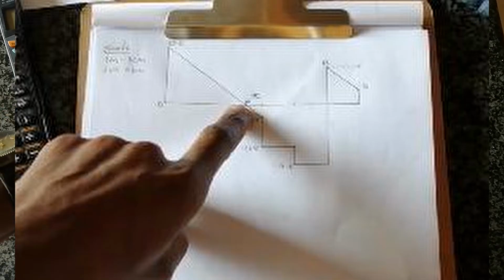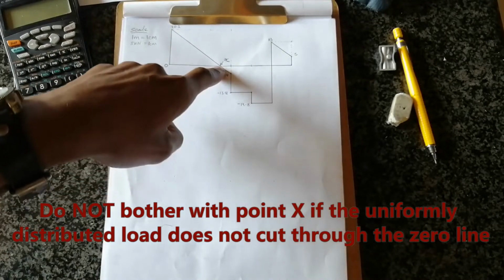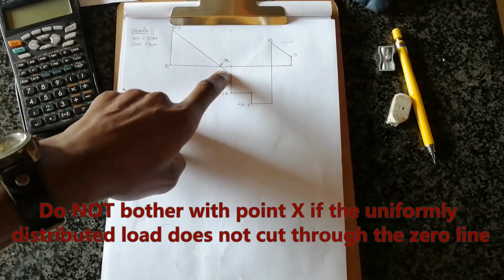At that point, that's where we have the maximum bending moment, and we also have the turning point for our bending moment diagram. However, if the uniformly distributed load does not cut through the zero line, do not calculate for point X.